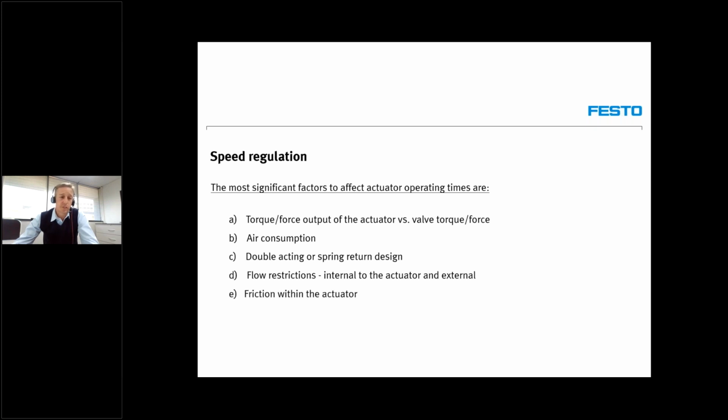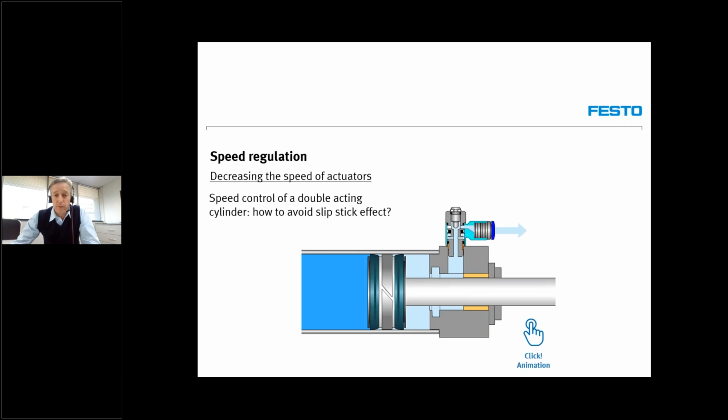And then also friction within the actuators. There are ways to keep friction inside actuators to a minimum, like keeping your air clean and dry and using the correct process valve for the correct application. Misalignment of those valves can put side forces on the actuator bearings, which could also lead to excessive forces and friction and ultimately failure of the valve or the actuator, or perhaps both.